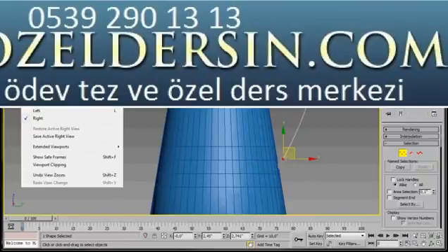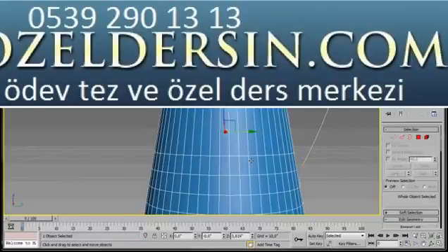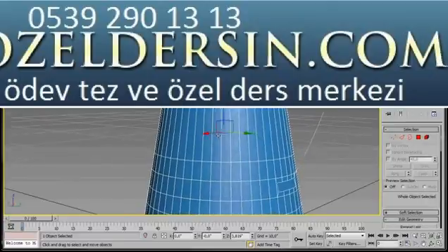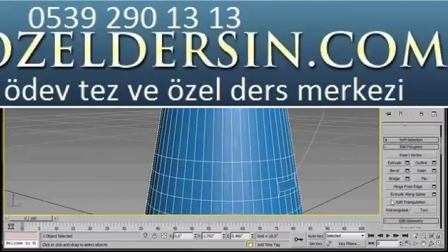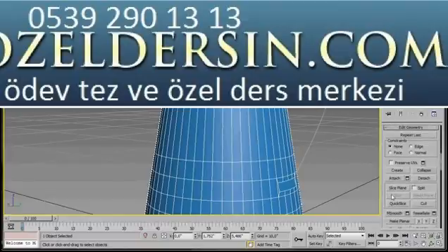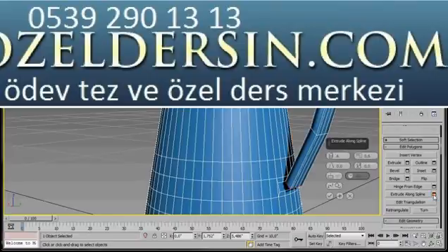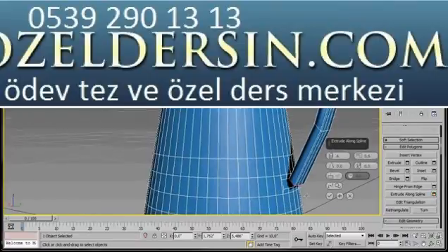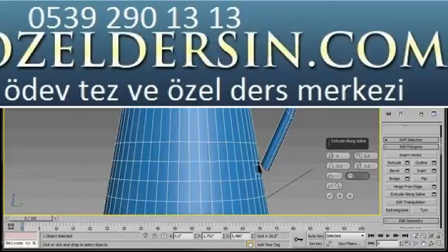Let's go back now to the perspective viewport. And now we'll turn off our line, select our object again, go back and select our polygon, and we'll go over to Edit Polys, and we'll click on the small settings icon for Extrude Along Spline. Okay, now here in the caddy, look, that's a good distance. You can see I have a distance there. You can see the segments.